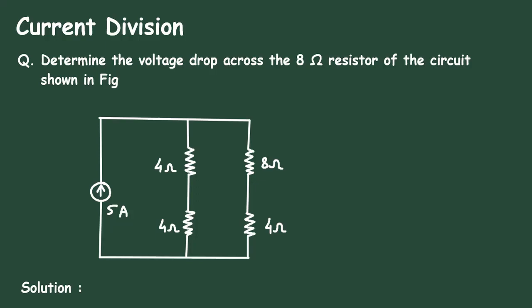Voltage V2 is 150. So this will be minus 150 divided by resistance R2. So resistance R2 is equal to 25 ohm. So therefore I2 is equal to minus 6 ampere.